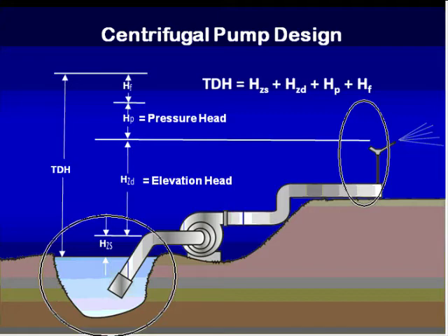The first part that we're going to look at is the suction head elevation difference between the water surface that we have in our impoundment or river that we're pumping out of up to the inlet of the pump. And so the HZS here that we're working with is the elevation change between those two parts, and there's a maximum value that we can have for that, and I'll get back to that here in a little bit.